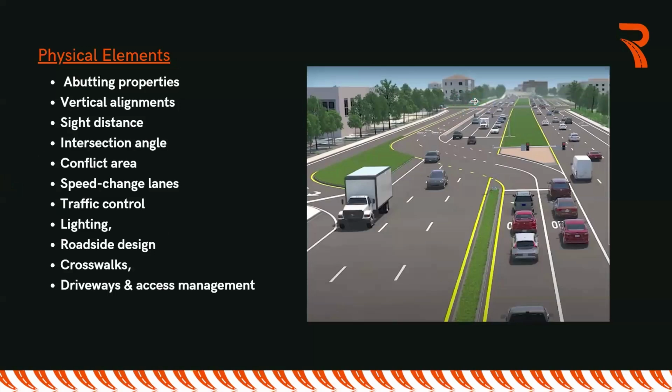And ideally, this type of displaced left turn allows you to displace the left traffic on the left lane before it gets to the main intersection. So you are deflecting the left traffic here, the left lane, before it gets to the intersection. And then, of course, this section is controlled with a signal at this specific point.